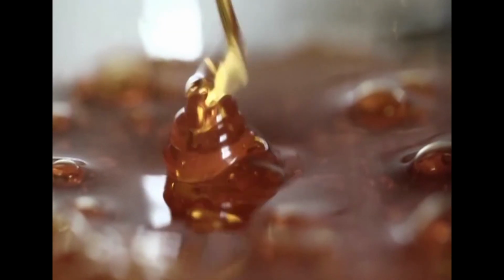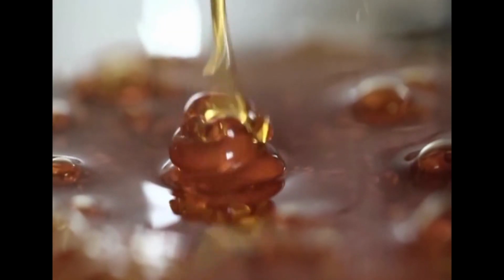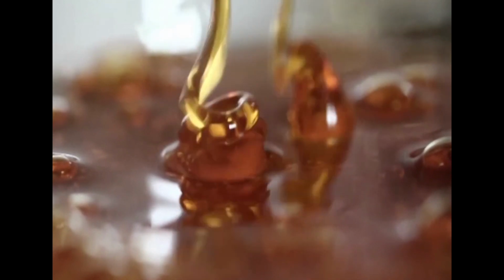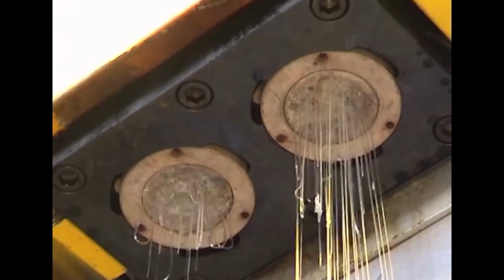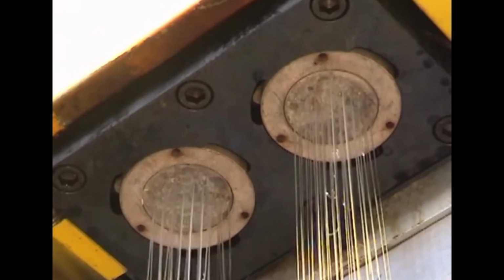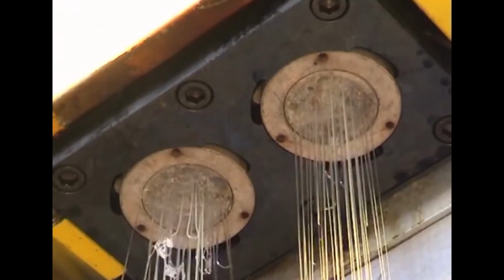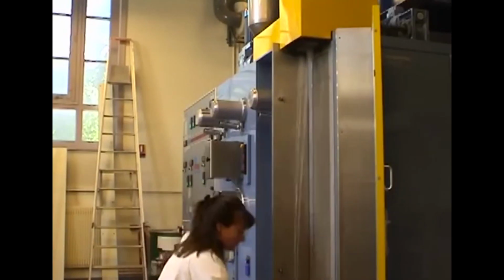For free flowing, this solution is required, because the polymer is extruded through the holes of a spinneret, which is a small metal plate having fine holes. The polymer in solution form is made to pass through the holes of the spinneret, and then it gets solidified when it comes out, and thus you get a continuous filament out of it.